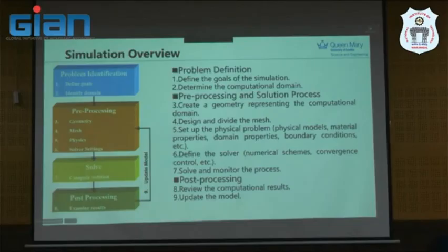Also, we should prepare different mesh or geometry files. And after that, we should create a geometry and prepare the mesh file, and then set up the physical problem, such as selecting the models, inputting the material properties, and setting the boundary conditions and so on.